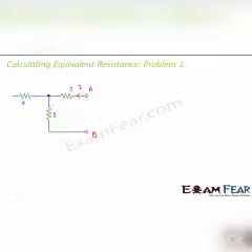When I reaches this point, it has an option to move through this resistance and another option to move through this resistance. But if you look, this resistance is in air. It is not connected to anything. So the current cannot flow through this. Let us suppose you keep a piece of wire on the ground, will current flow through it? It will not, because in order that current flows through a circuit, the circuit has to be a closed circuit. There has to be a battery connected to the circuit which will provide the potential difference between the two ends of the wire. But in this case, this wire is hanging in air, so no current can flow through this wire. So the entire current will flow through this resistance.